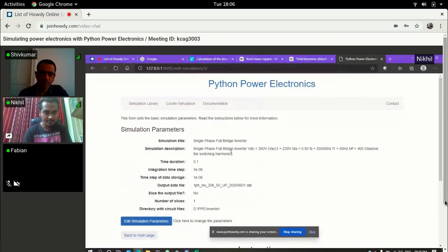What do you want to see in this? What exactly would you like to do? Let's simulate together. That's the idea. What was it that you wanted to find out? After simulating, in the output section we get scopes with output voltage, current, or whatever you are sensing, but only in the form of waveforms. What if we want to generate a report based on whatever we are simulating and quantify the outputs, like the output is 230 volts RMS? How do we get the quantified values of the outputs?